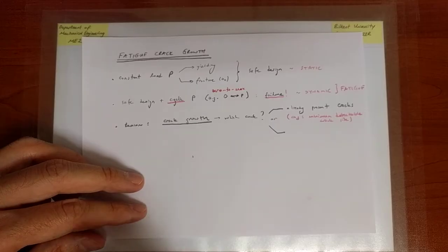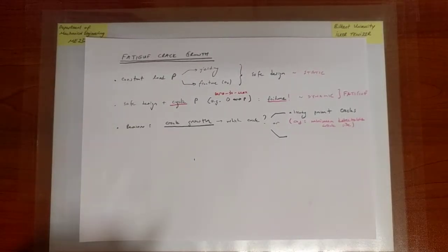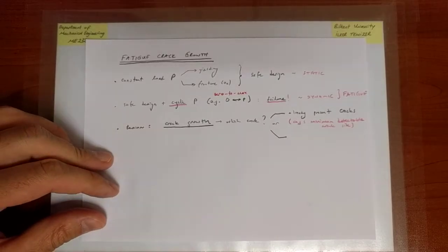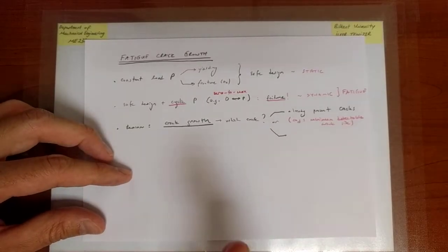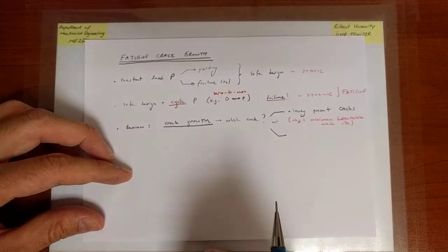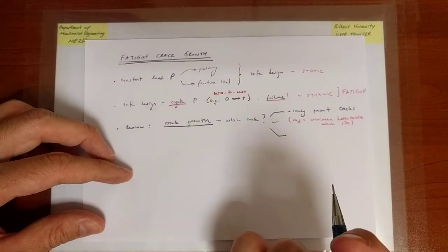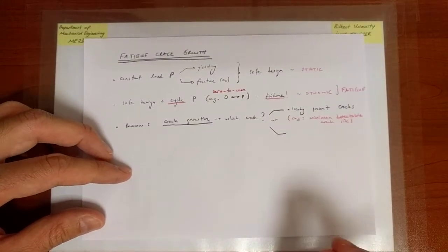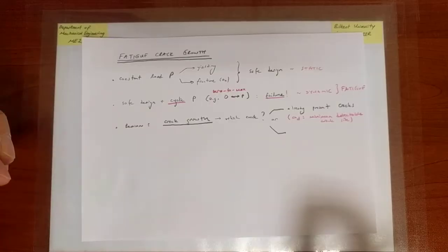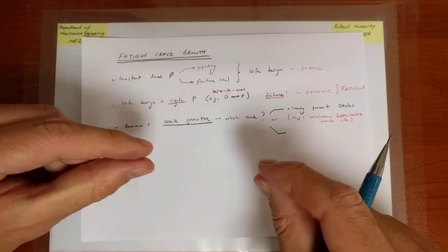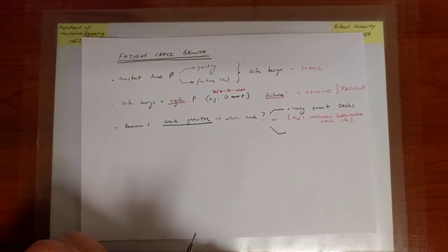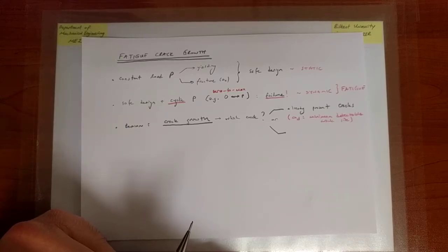Suppose you have an extremely well regulated manufacturing process and there is no crack. A crack has a definition: it's like a void with a very thin geometry, almost like an ellipse that has no thickness. That's the way, in fact, we derived it when we were talking about fracture mechanics.